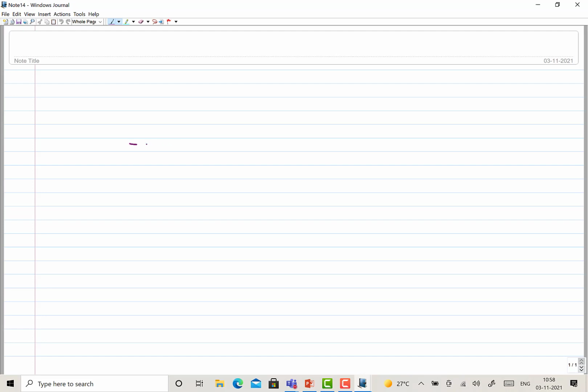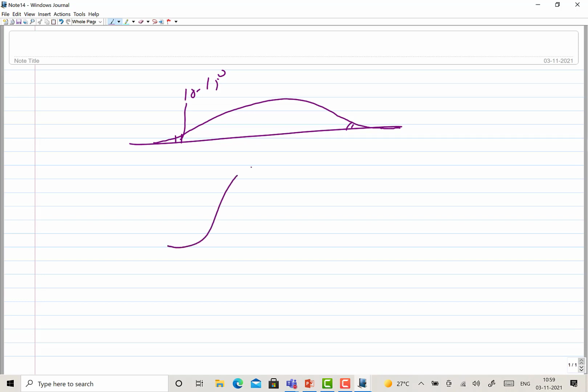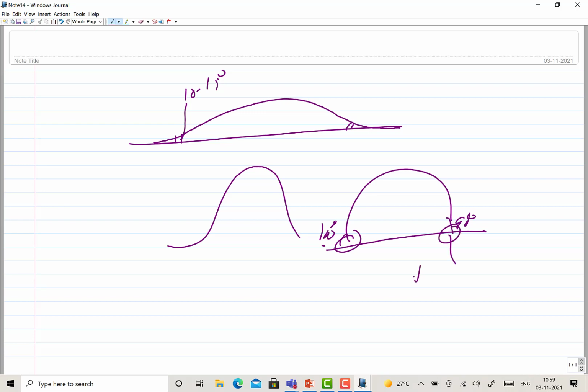What is that? We always expect that the weld bead is deposited like this, so the bead angle is low. So there is no sudden change in cross section. Maybe it is good if it is a 10-15 degree bead angle like this, but if the metal is deposited like this, in this case it may be like a 100 degree or 90 degree bead angle. This sudden change in cross section causes high stress concentration, and high stress concentration frequently causes cracking or fracture initiation at the toe of the weld. This is the toe of the weld, this is the bead.